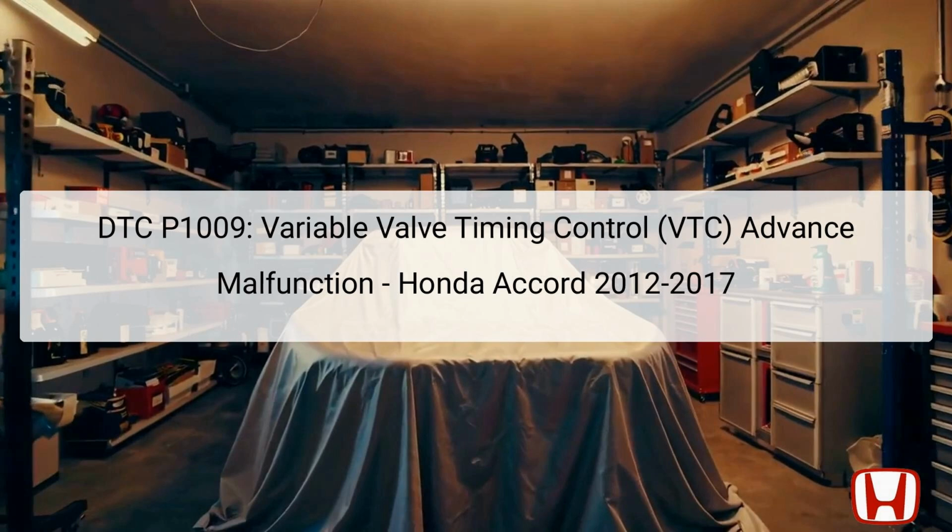If the camshaft phase angle is excessively advanced beyond necessary specifications, the Powertrain Control Module, PCM, will flag this issue. It's crucial for maintaining emissions controls and ensuring adequate engine performance. In the following slides, we will delve into the details of the malfunction, potential causes, and systematic troubleshooting steps to resolve this DTC effectively.